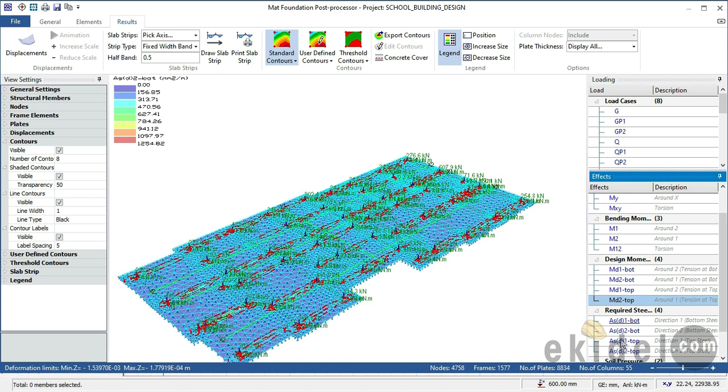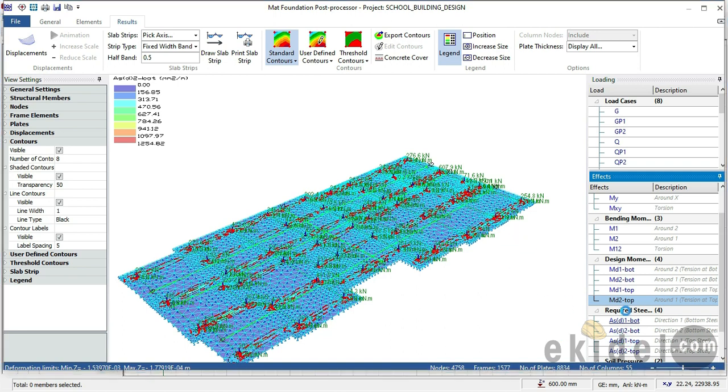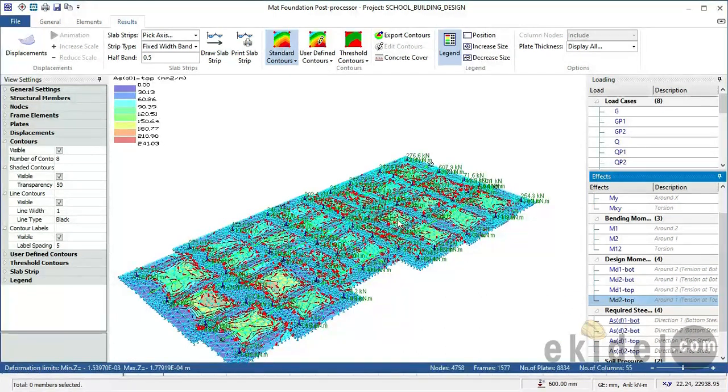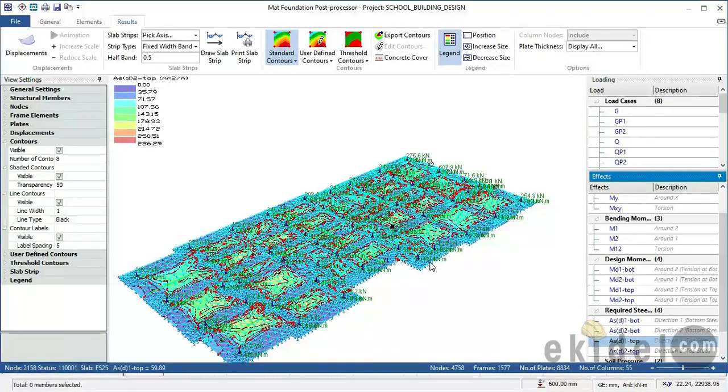So right now I'll click on the top one because I've already clicked on the bottom button, as you can see there. So I'll click on now. As you're clicking here, if your slab depth was not sufficient, you will be seeing an error. Once you get to this stage, once your slab thickness is not sufficient, you will begin to see errors like insufficient depth errors. So once you see that kind of error, you have to go and locate that slab and then increase the slab thickness, generally only for the raft foundations.